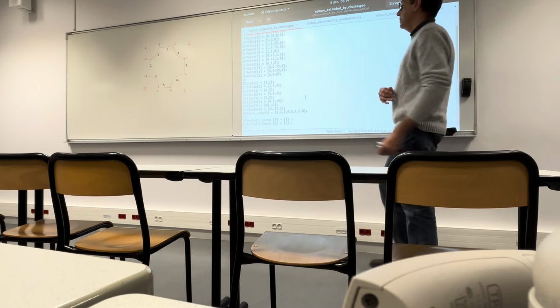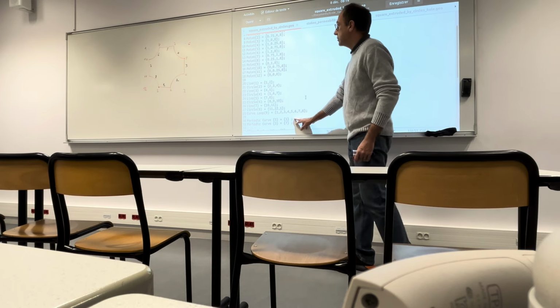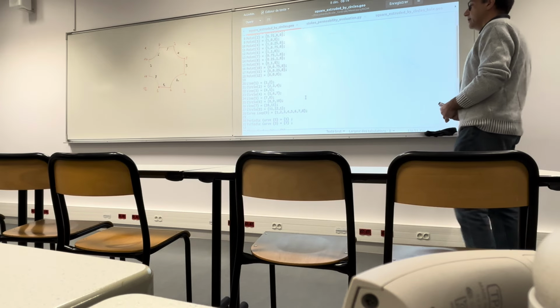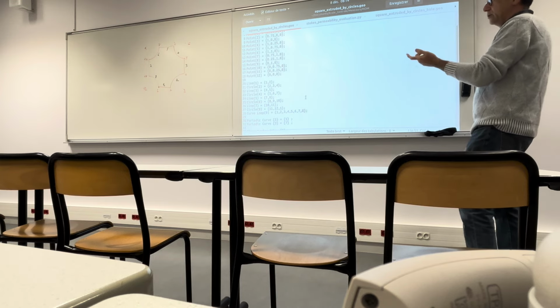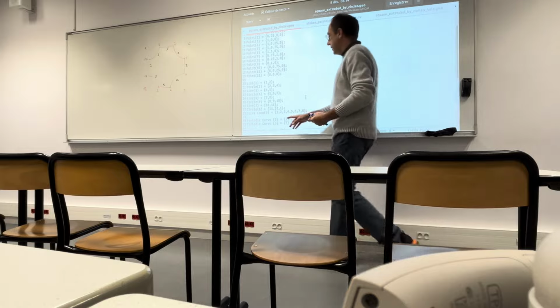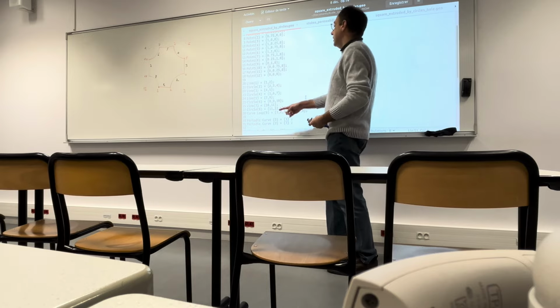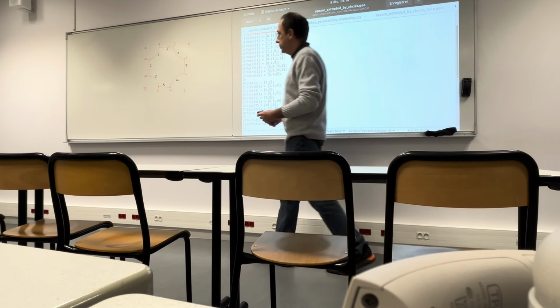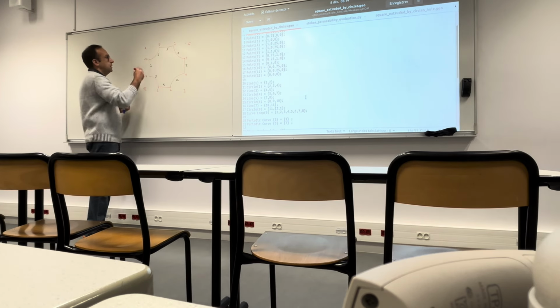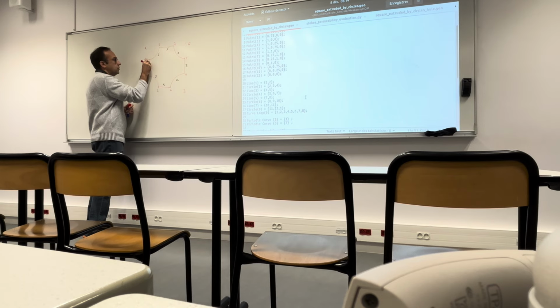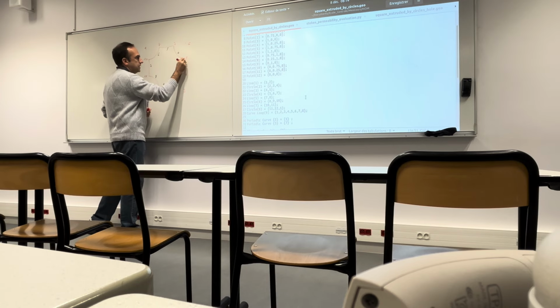Then, as I was telling you, this condition is specified in order to guarantee that the further discretization that we are going to introduce later is respectful of periodicity, in the sense that we want to generate a discretization such that the same number of nodes are placed on the left, for instance, and on the right side, and the same for the bottom and the top.